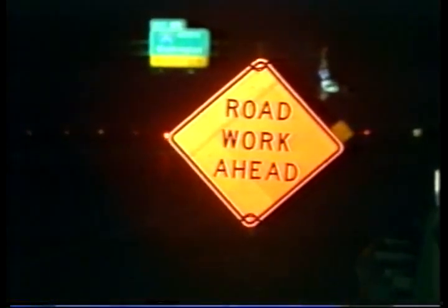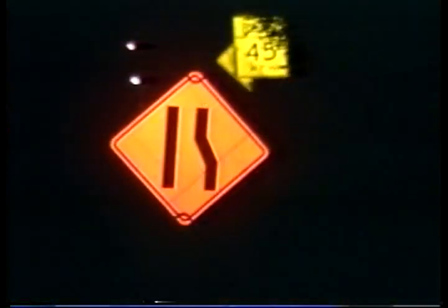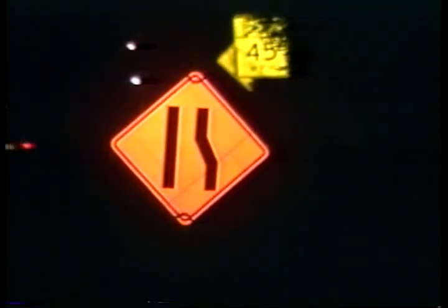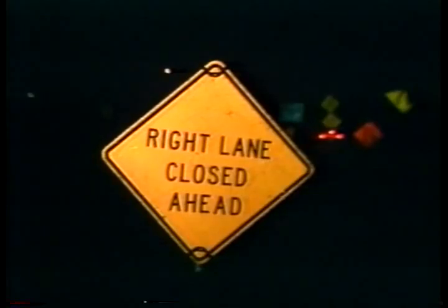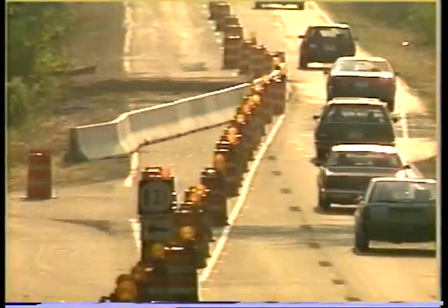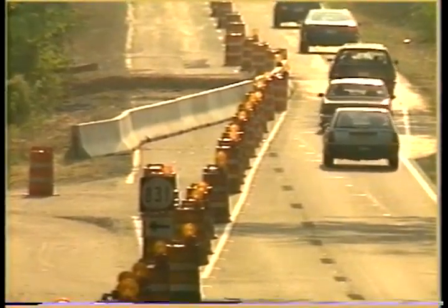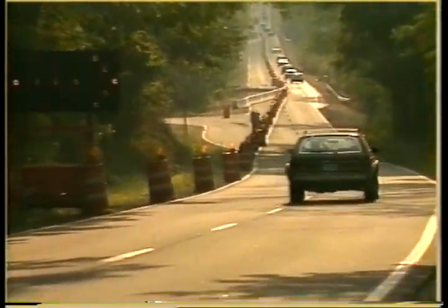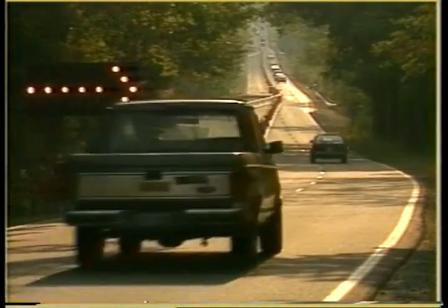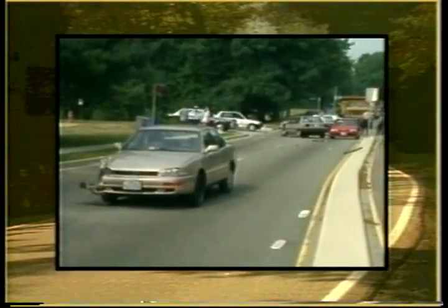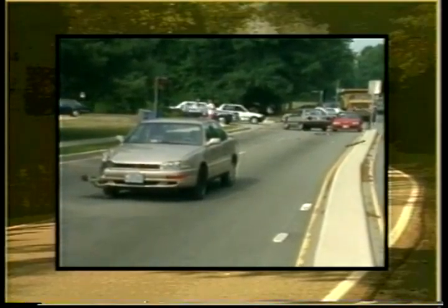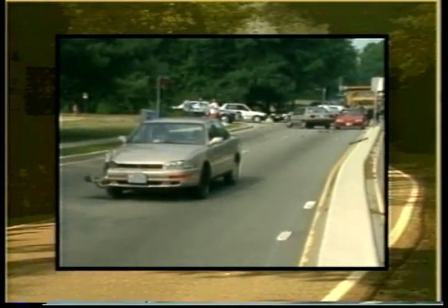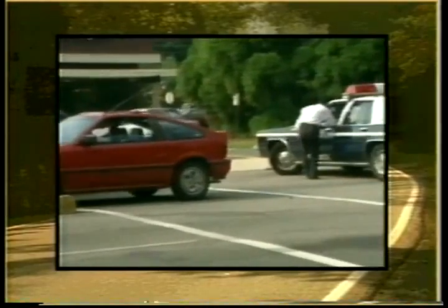Subsequent inspections may be done as a drive-through, and there ought to be inspections at night. On-site inspections are not the only way traffic control plans are measured. To evaluate the impact of the plan, there is also a cost-benefit analysis. It is based on a series of measurements, including accidents. The estimated work zone accident rate is directly related to the accident rate prior to construction and the average daily traffic on the route.